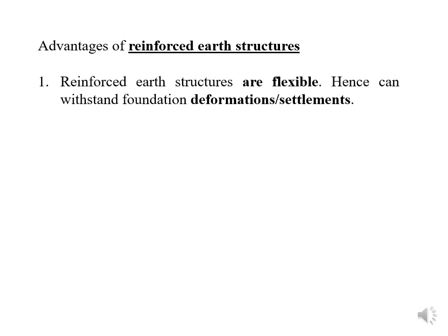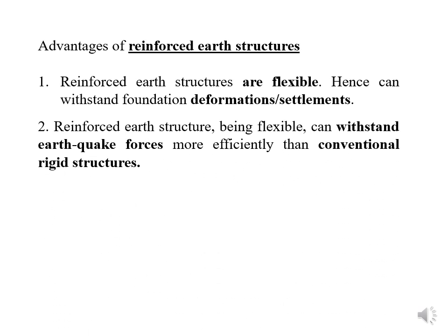Reinforced earth structures are flexible, hence can withstand foundation deformation or settlement. It is flexible because you are going to use the reinforcement. And being flexible can withstand earthquake forces more efficiently than conventional rigid structures. If you construct rigid structures, they will not withstand the earthquake forces, but this can withstand.